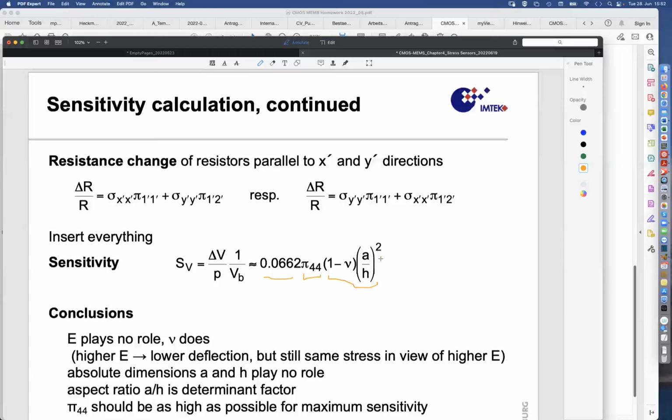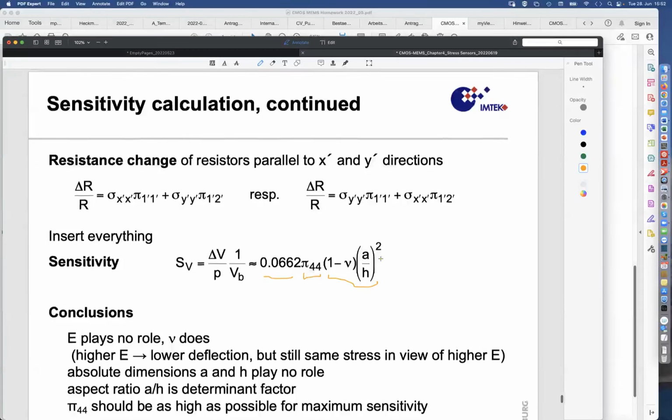So if you would like to have a larger pressure range, I'm sure that making the membrane smaller and smaller will let you reach that larger pressure range, because the membrane has better chance to remain in this linear regime than if you have a very large pressure range.